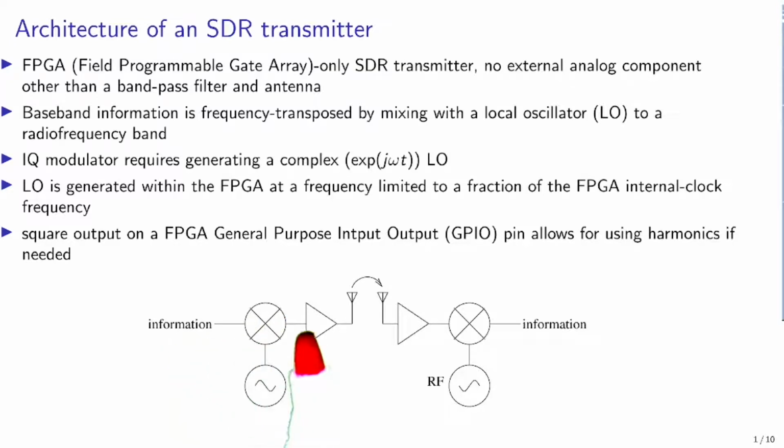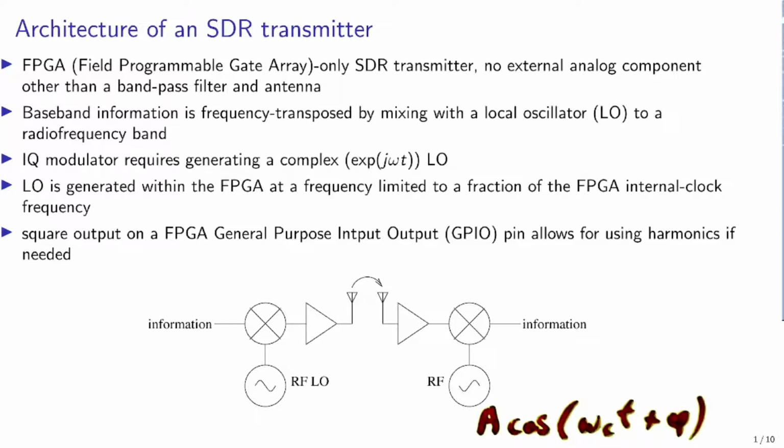This modulation step will imprint the information on one of the 3 quantities representative of a radio frequency wave. We have something of the shape amplitude times periodic signal and a phase, and all these quantities can carry the information, in terms of amplitude modulation, frequency modulation, or phase modulation. The resulting communication will be received by the receiver, and the objective is to remove this intermediate radio frequency carrier to recover the information that was transmitted.